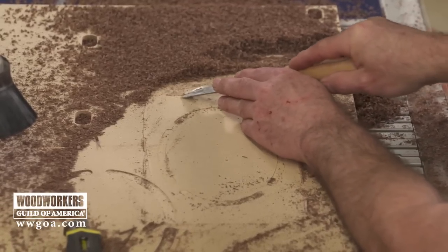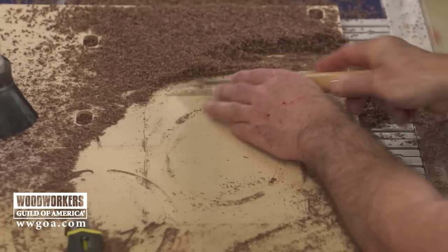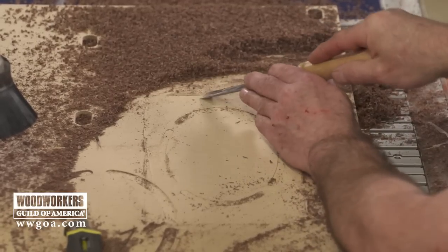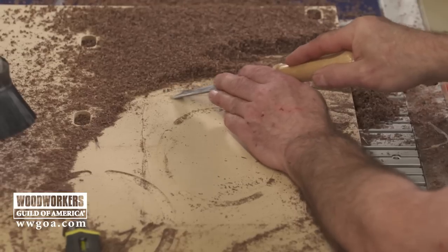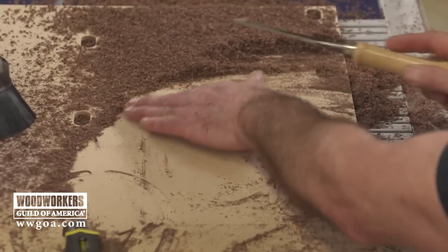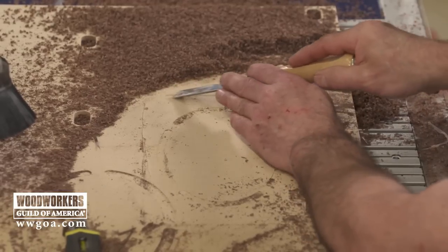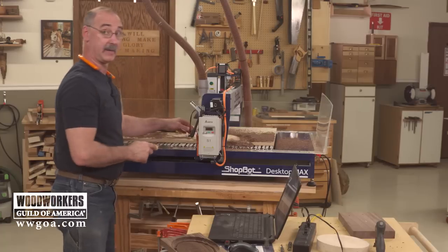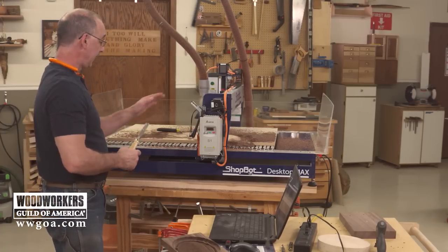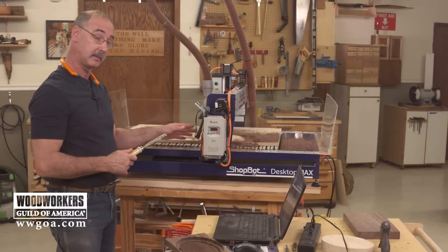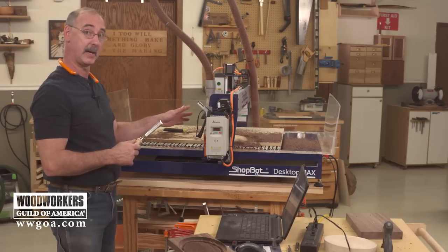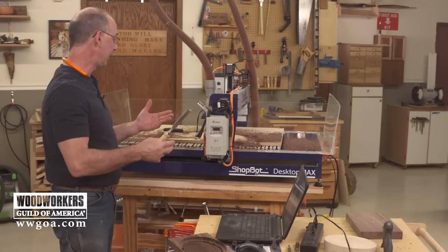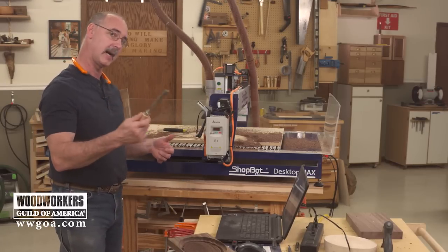Now these are called spoil boards. Eventually, we're going to get so much junk and so many cuts on here that we do what's called fly cutting, and we resurface this whole board, so that little bit of glue doesn't bother me. Here's what I'm going to do. We still have to cut our base. So I'm going to get the base hot glued in place. I'm going to recenter. I got to change my cutters. We're going to do that base with a 1/2 inch bit. I'll take care of all that work. Then when you come back, we'll be ready to run.